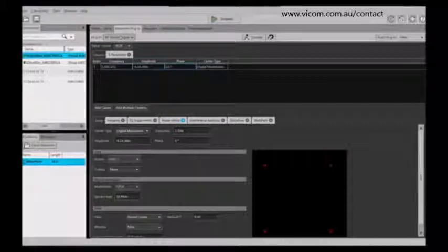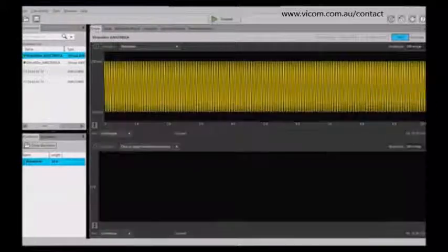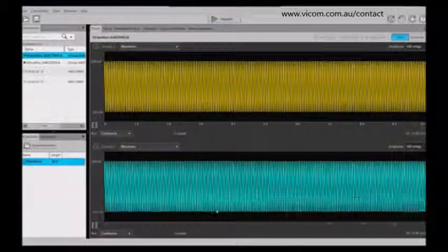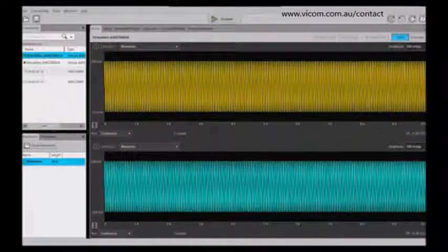Here we're using the RF generic signal plugin. The other toolbars at the top of the screen are the same as on the AWG itself. Home display would give you the display of the actual waveforms. This is a two-channel box, so you can see that I could actually drag the same waveform into both channels. And then if I wanted to play them, I could just play them here.